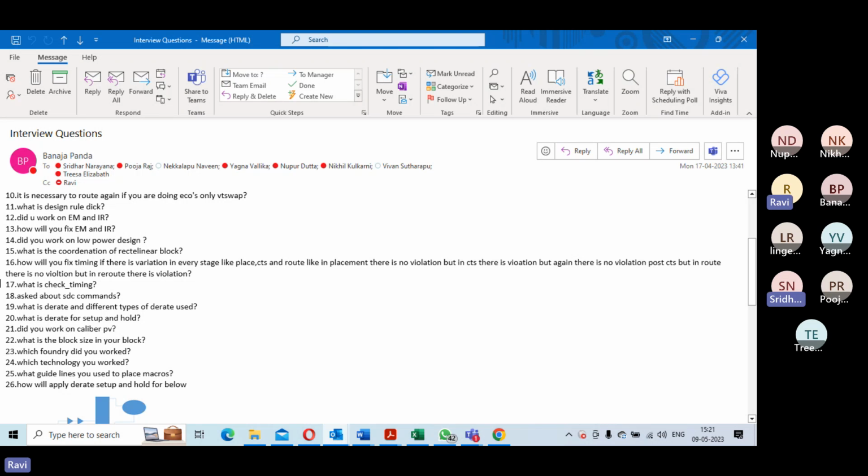You split the net, what will happen? The current going through the trunk of the net will reduce, because it's only feeding a smaller portion of the fan-out rather than a bigger one. So the fix is: reduce the fan-out, split the net, increase the width of the wire, or reduce the size of the driver. If you have put a big driver, it is driving huge current. That is why you are not using any 24x or 32x drivers. Why do they put a stop on using big drivers? Why should they prevent it?